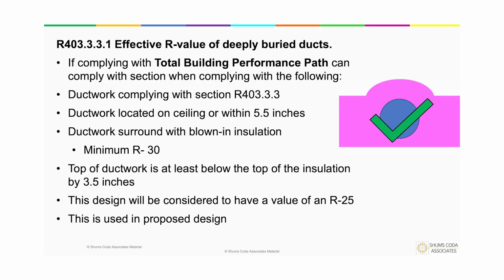All right, now, this is the effective R value for deeply buried ducts. Now you'll say, hey, Hope, didn't we just discuss this? And I'm going to say, yes, we did, but we did it for those that are utilizing the prescriptive compliance path. If they decided that they were going to go with the total building performance option of the compliance paths, and they wanted to show that their ductwork was inside conditioned space, this is the section that they would have to utilize.